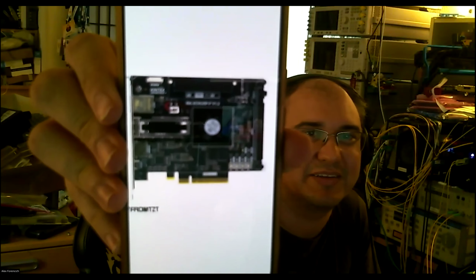Okay, and the one I found is a PCI card which is about 500 euros. So yeah, that would be acceptable. I have to check. This is the board that I had in mind. Yeah, these guys. So it looked like what I found also. It looks a bit more expensive. There's a gigabit Ethernet, there's an SD card, there's a USB-C debug port, FMC port, a big 40 pin header, I guess for IO, and QSFP28. Okay, so it's all useful.